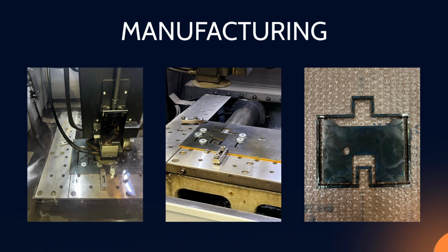The types of cutting used were laser cutting for the holes where the wire of the EDM system would be inserted, EDM cutting to define the geometry of the component, and milling for the V-grooves. The operator needed to trace the path of the EDM machine in order to optimize the movement of the wire and the time necessary to finish the piece.